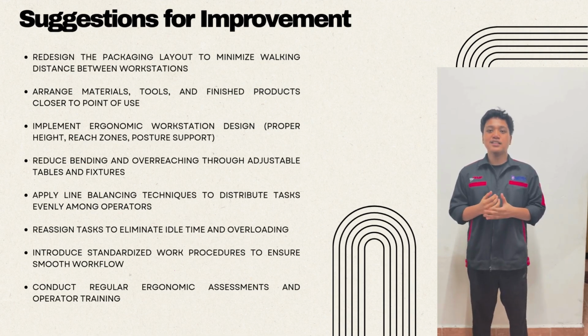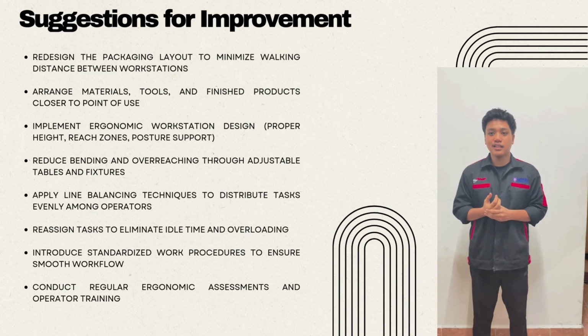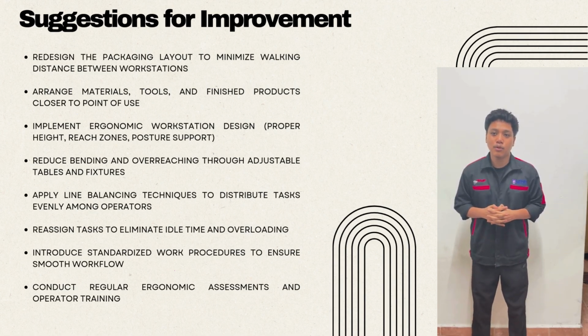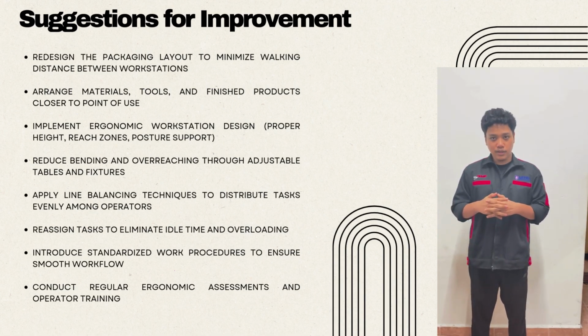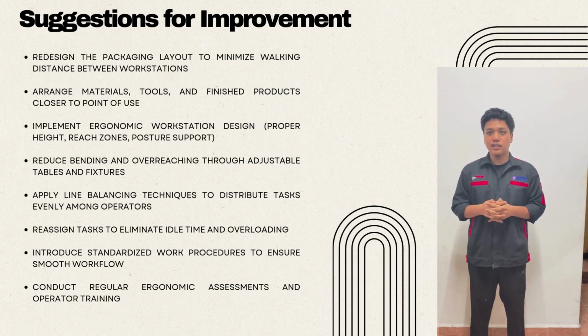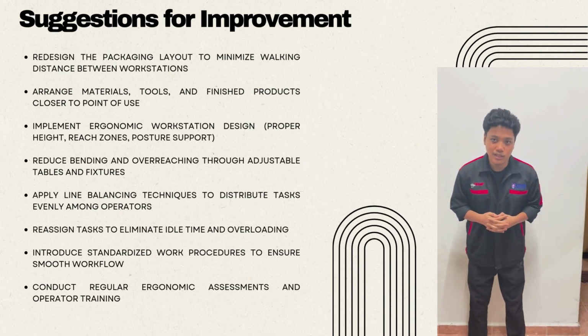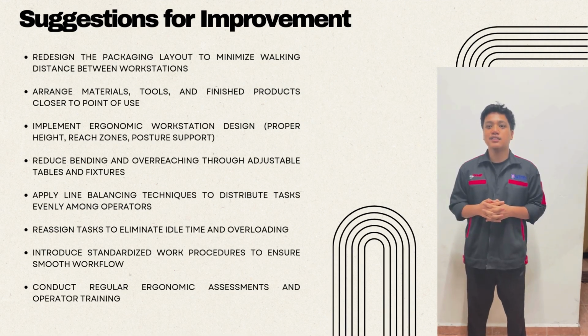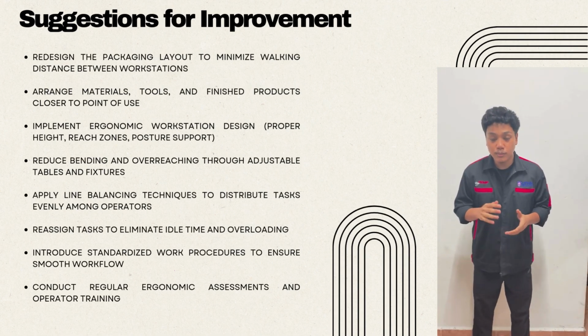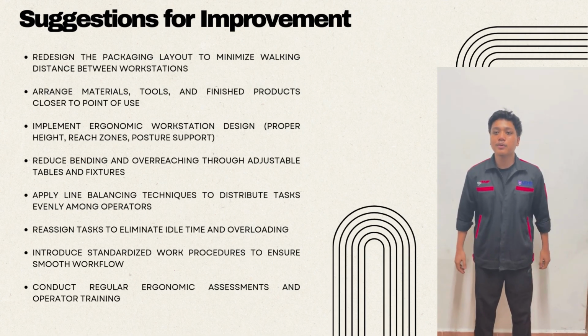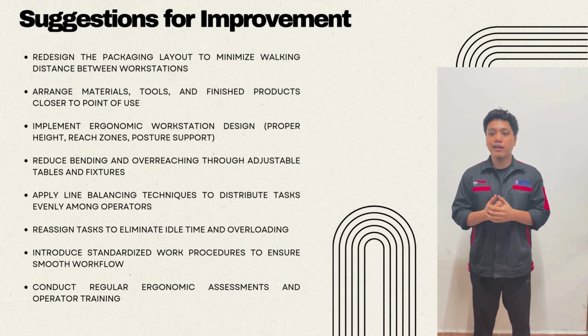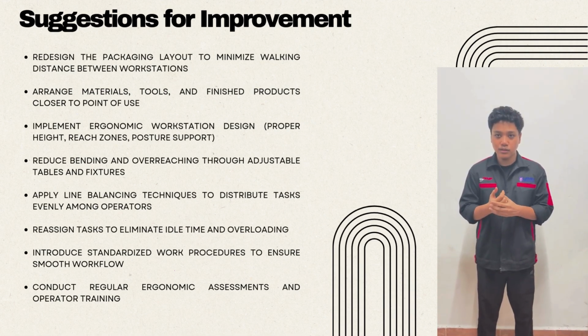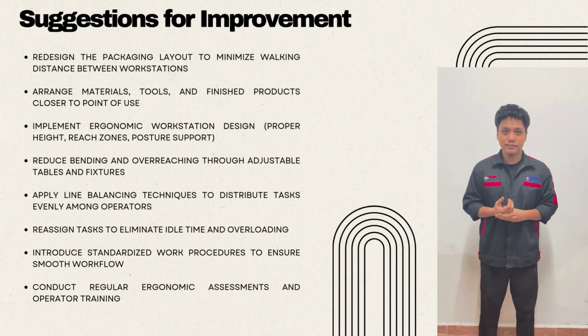We also suggest applying line balancing technique so that the work is distributed more evenly among operators. This will help reduce idle time and prevent overloading. Lastly, standardizing work procedures and providing ergonomic awareness training can help ensure smoother workflow and better working posture.